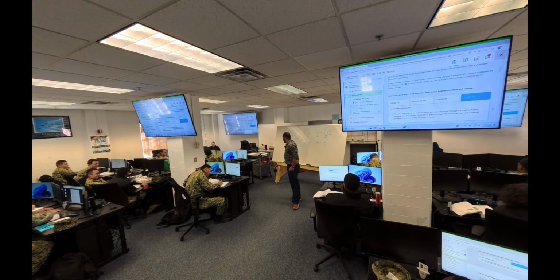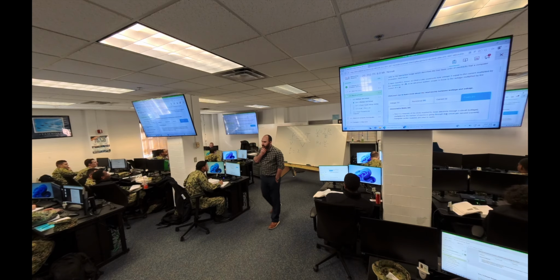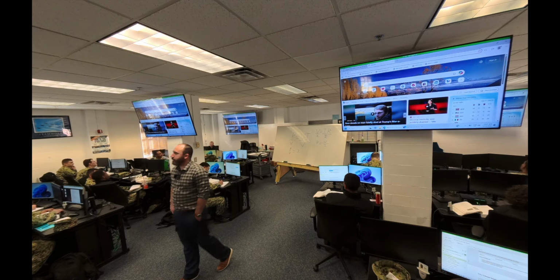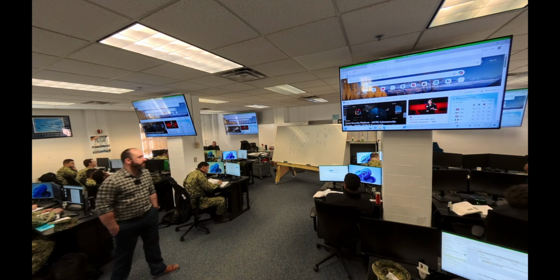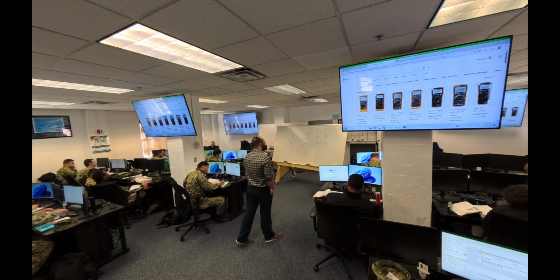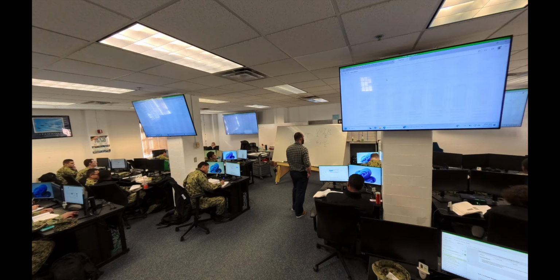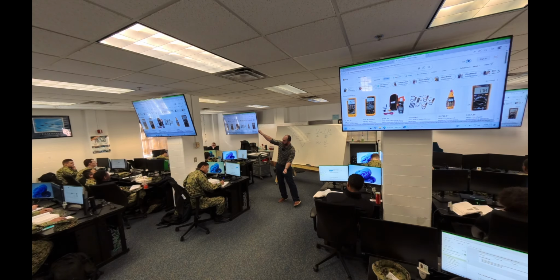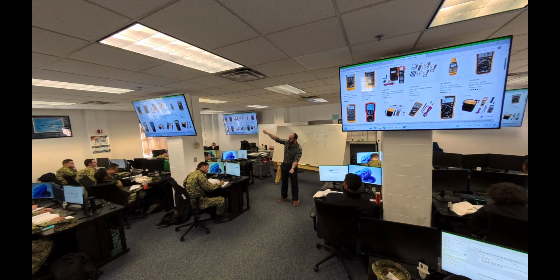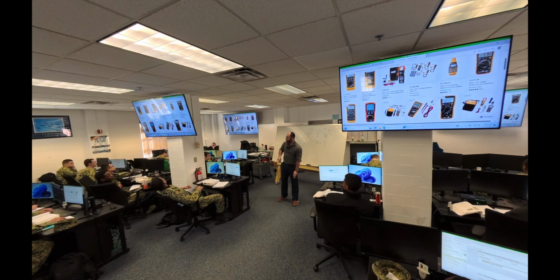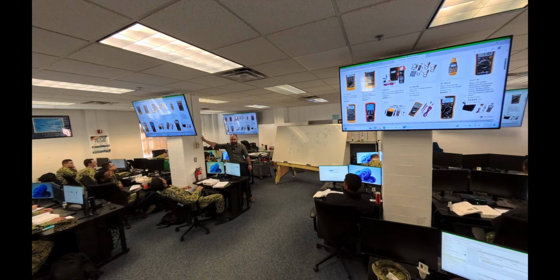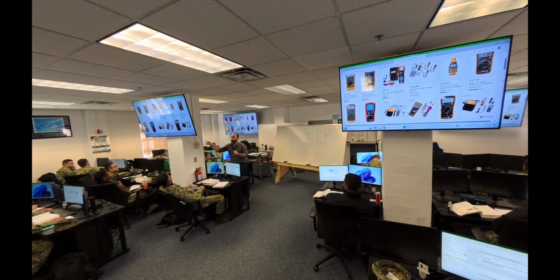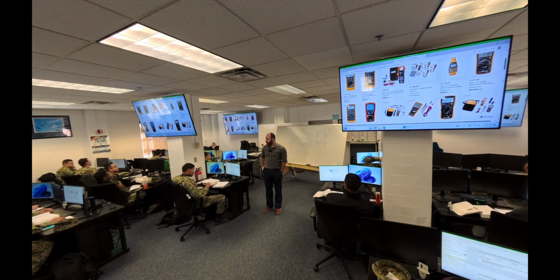Okay, so we've got a multimeter. Could you pull up an image of a multimeter for us? And we'll see this in later chapters. So you can set this to different things. You can set it to ohms, etc. And you'll actually have a red and a black lead on this. You'll place one on your equipment, one on the rack. And you can test to see how much resistance is going through here. If I'm touching here, and there's a path of electricity between here, it'll go through, right? And we can measure it with those two probes that connect to this, and it'll show up on that screen.